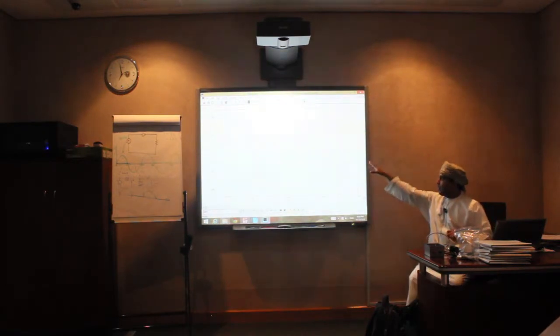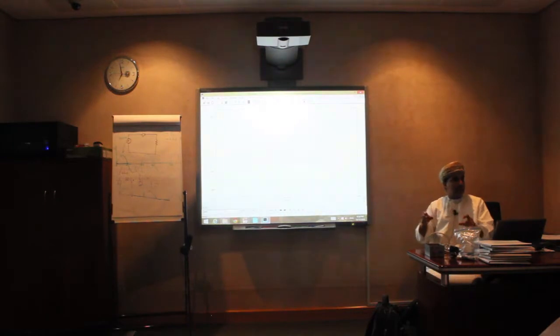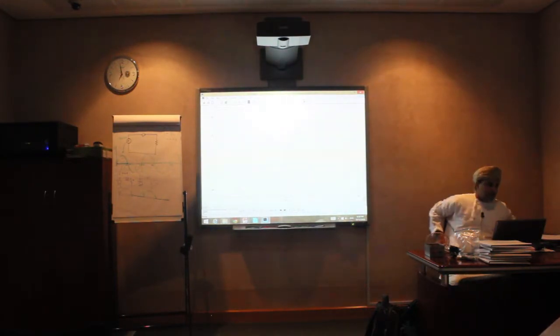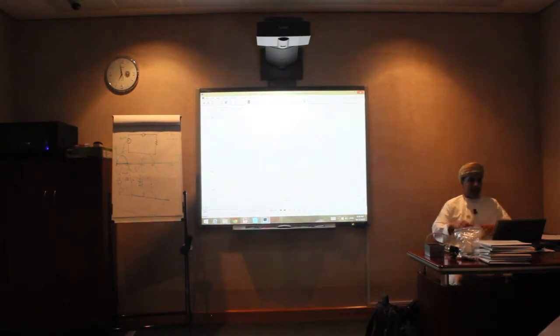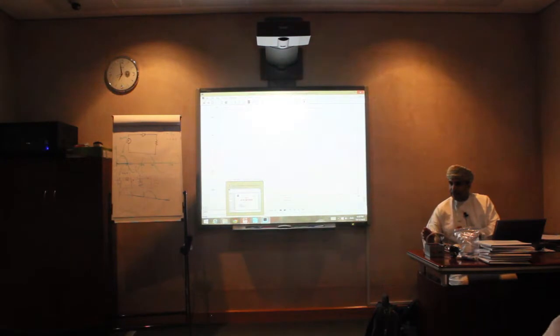The only difference is that until now I can see that it's not pure DC, it has some ripples, or you can call it harmonics component, and then later on it can be improved, or it can be filtered by such filters to decrease those ripples. So this is the first circuit, which is the basic circuit, which is known as half-wave rectifier.